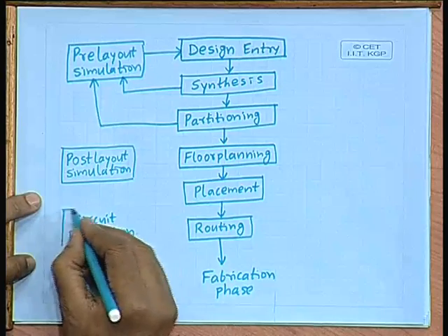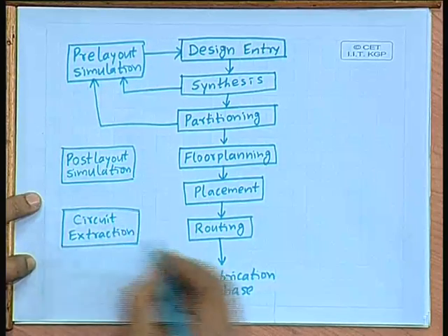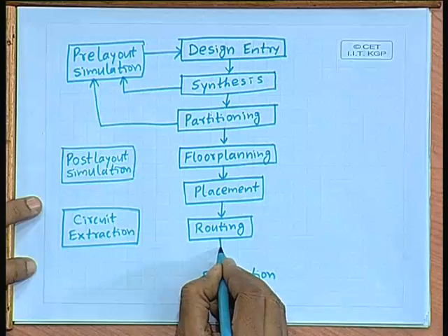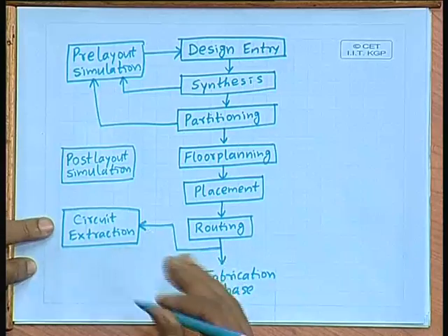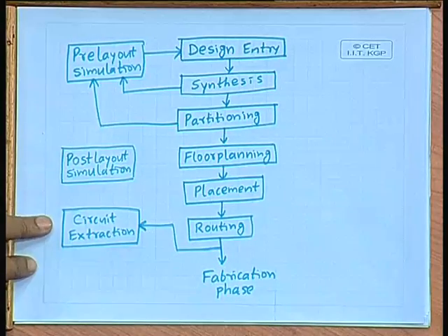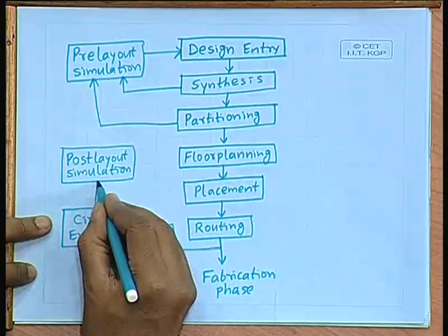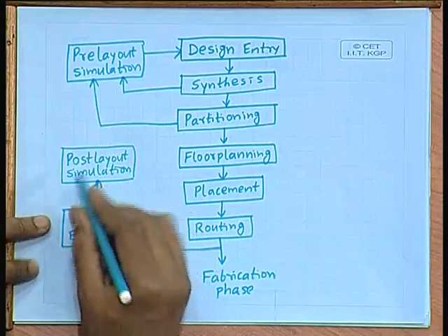What this circuit extraction step does is take the output of the routing phase, which is a layout, and from the layout it tries to extract back the circuit, and after extracting back the circuit it gives it to a simulator.